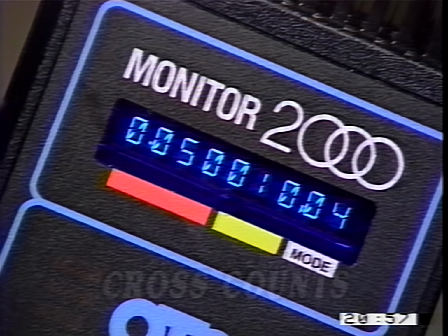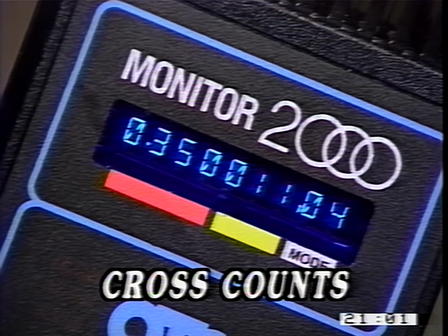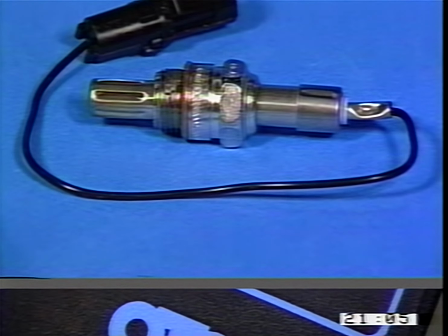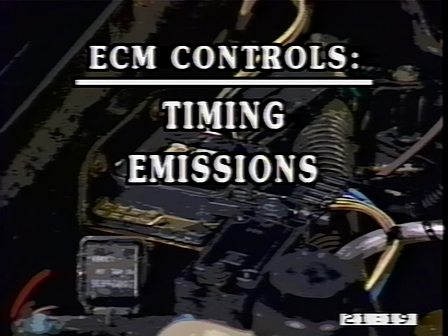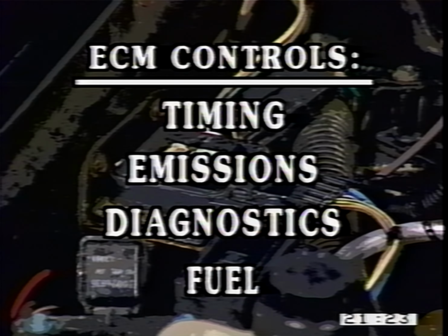The fluctuation is measured in what is called cross counts. These cross counts are used by the ECM for tailoring fuel mixture. The oxygen sensor will not produce voltage until it reaches 600 degrees Fahrenheit, 316 degrees Celsius. Based on these 5 primary inputs, the ECM controls ignition timing, emissions including the EGR and air pump control solenoids, diagnostics, and fuel control, our next area of study.